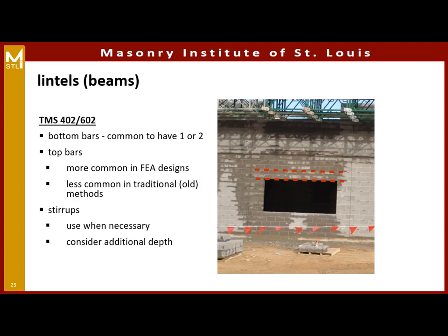Lintels are beams in masonry. It is common to have bottom bars in our masonry lintels. The standard way for designing masonry lintels was as a simply supported member, pinned at each end. So all our flexural tension is on the bottom. So we have bottom bars.